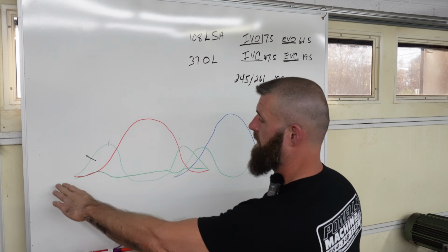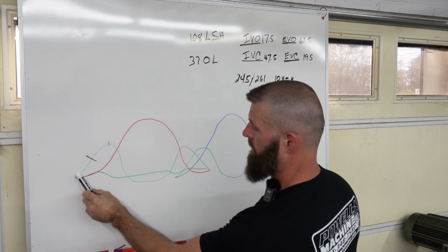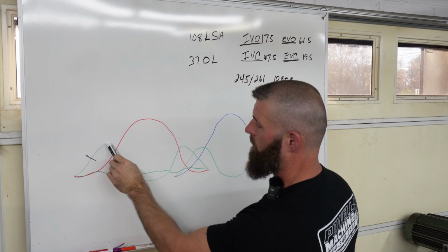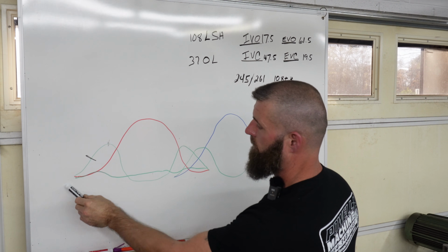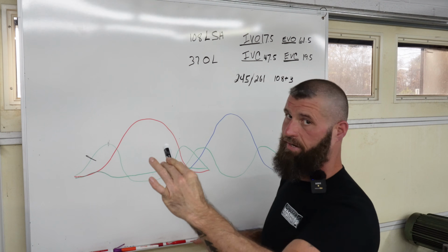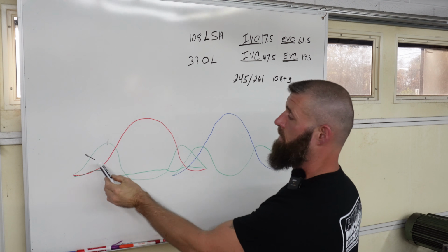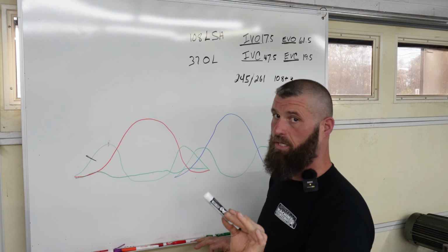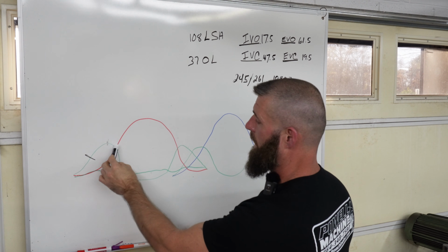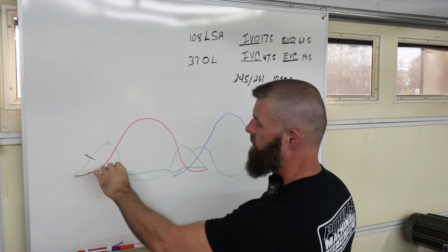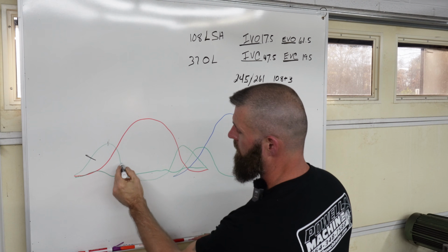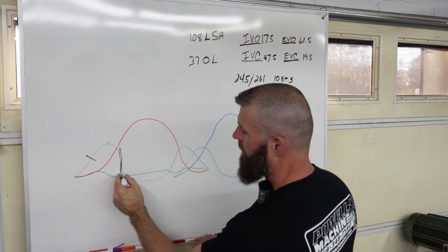So the lifter is coming up the lobe, and we're in tension all the way to here. At peak acceleration, the lifter and the whole rest of the valve train is in tension. When we get to peak acceleration, the system starts unloading itself. As it comes down to negative acceleration, peak jerk is going to happen somewhere around here.